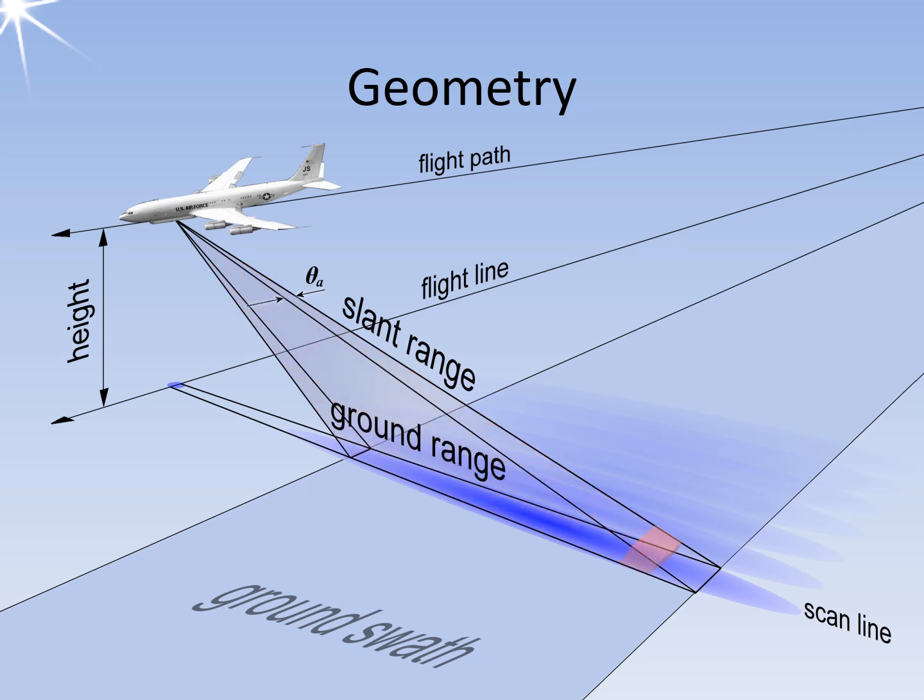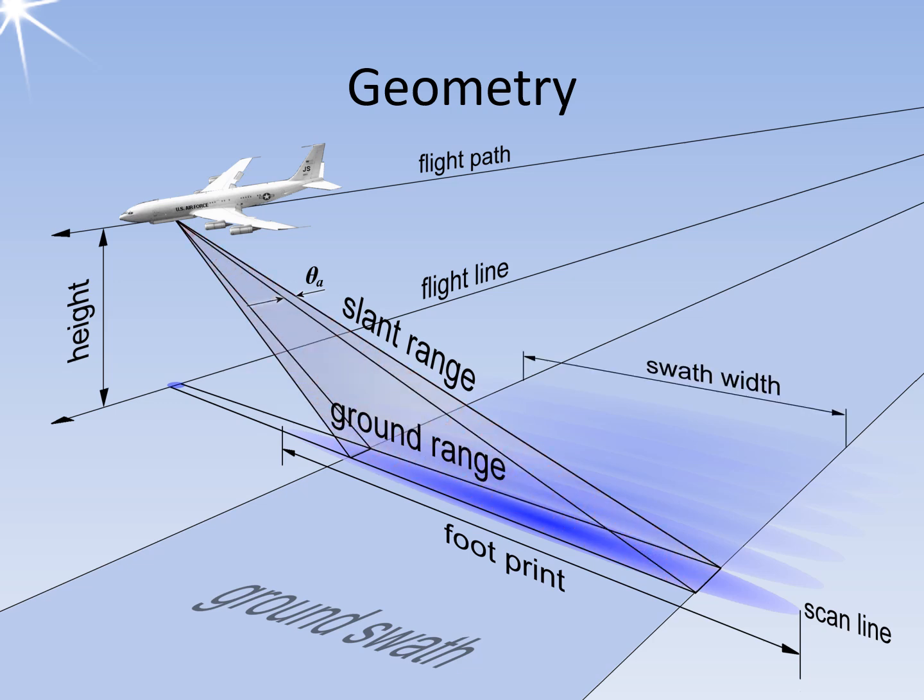The area swept by the radar is called the ground swath. The footprint is the area illuminated by the radar in the respective pulse period. The footprint is not the same as the swath width or the strip width of the imaging strip. The horizontal distance that can be used for image generation in practice includes only the widths where the various footprints leave no gap. The swath width is obtained from the horizontal antenna pattern and the flight speed. The horizontal antenna pattern can be derived from the antenna length L. Caution: when observing, the beam angle or nadir angle theta is not always equal to the angle of incidence, theta I.